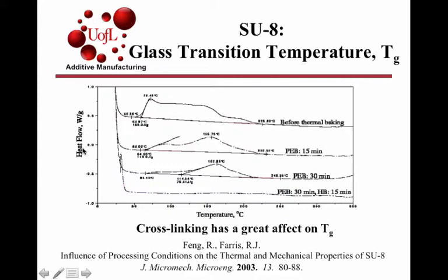We saw a version of that when we were looking at one of the research articles in module 1, and we'll look at some more of those aspects as we explore research articles in module 2. And here you can see that basic reaction exotherms change with different curing conditions. Accordingly, glass transition temperatures and the endotherms related to that change as well for the cured material.